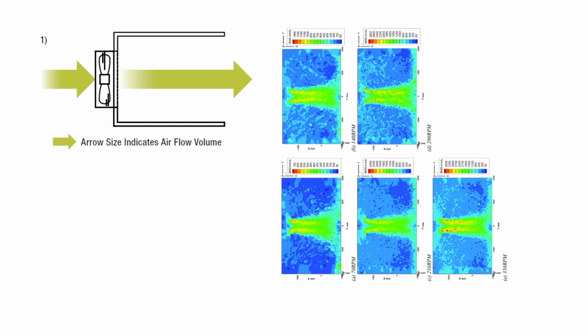So that's why I created the case simulation test, and why I don't particularly like the CFM test. CFM is good if you're doing one of, I think, three things. If you want to make your own at-home wind tunnel, it's basically CFM. If you want to generate PQ curves for testing, generally testing data for how good a fan is in different pressure applications, like Noctua does, CFM testing is again what you want.